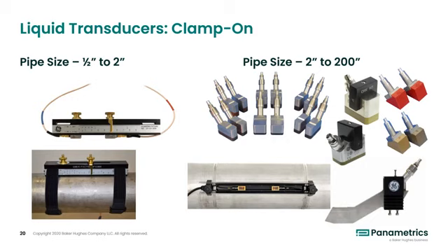Liquid clamp-on transducers come in many different shapes and sizes, but all are compatible with each of our clamp-on products that we mentioned earlier. For smaller pipes, the CFLP integral transducer mounting bracket allows for easy spacing, measurement, and placement. Additionally, the other integrated rail just to your right is what is used for the AT600, allowing for a quick, easy, and consistent installation.